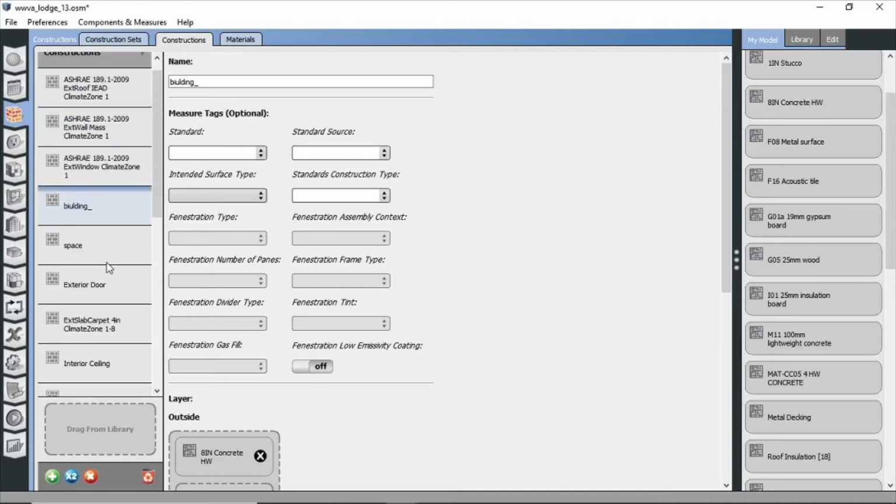After creating these constructions, it's time to characterize the shading elements. It is noteworthy that these materials that we are using randomly only try to approximate their real composition. However, you can create new materials, edit these properties and add them to your library in case you need something more specific.